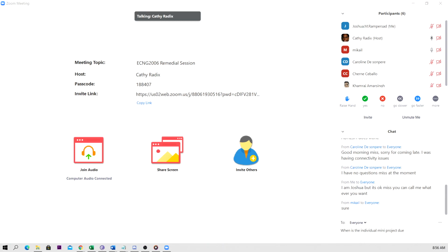Any luck, Mikhail? The last thing I'm saying here is the BCD hypo. BCD hypo, okay. Anybody had any issues with representation on BCD? You're going to need BCD for displaying the digits. Well, we're only using one 8-bit display on our practice board. But BCD is useful anytime you want to display multiple 7-segment digits. So any queries about BCD?